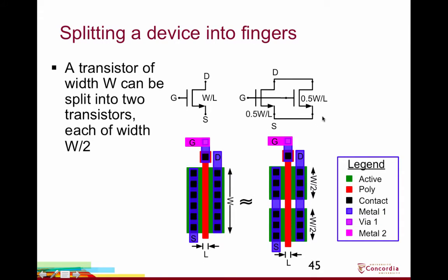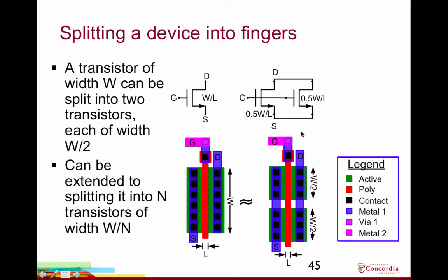Now remember from the review of the IV characteristics that all of the expressions for current were proportional to width. And that proportionality to width is going to be true whether or not it's a nanometer transistor or a much larger feature size transistor. We might get some narrow channel effects when width gets close to the minimum, but for any non-minimum width transistor, current is proportional to width. Okay, so we haven't really done anything special here. We've just got these two transistors in parallel.